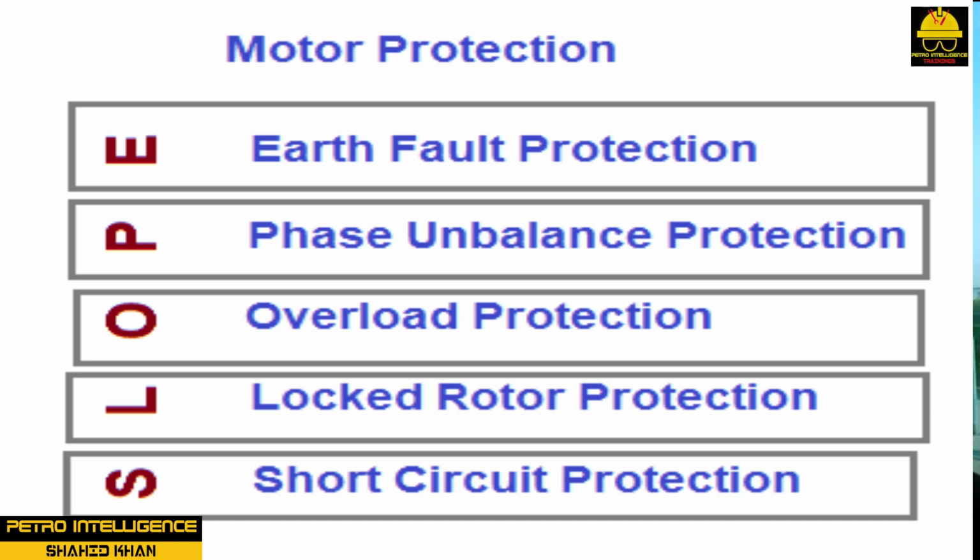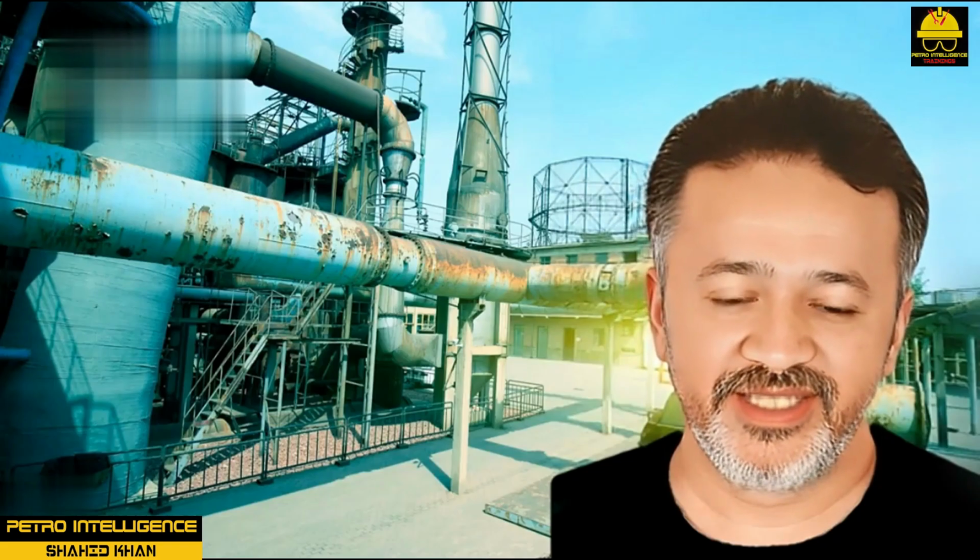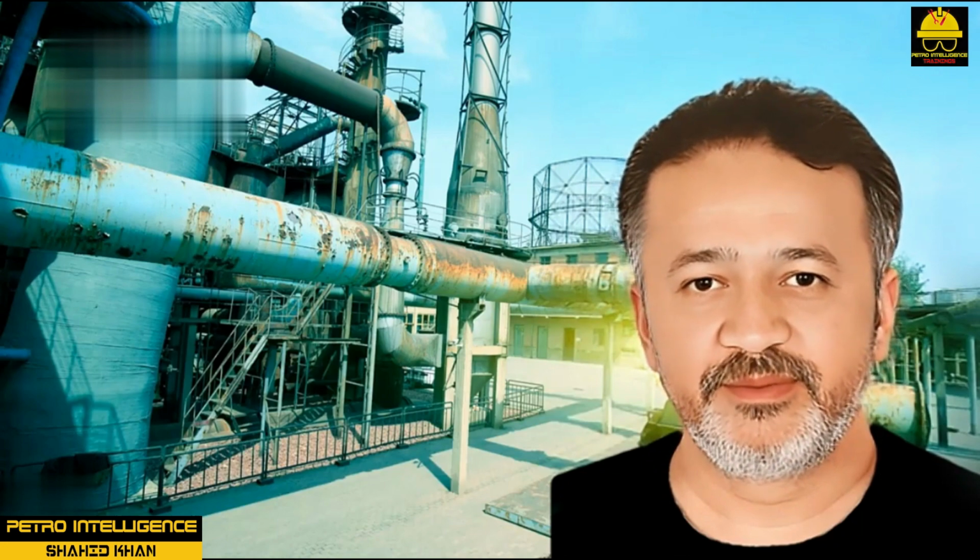Large-scale motors have the same type of protection, generally called circuit breakers. These breakers, located in the Motor Control Center, MCC, actually afford 2 types of protection. One type protects against the instantaneous very large overload, such as might occur if a short circuit develops in the system. The other is a thermal overload that protects against continuous operation at a high motor loading. Either of these devices can shut down a motor. Knowing which of these devices was activated can be a clue as to what is causing the problem.